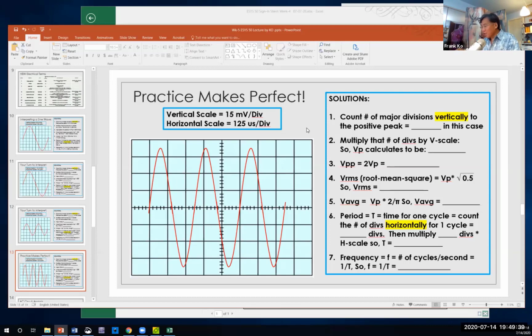If you put a straight edge, what you do is you get a piece of paper and you just put it as a straight edge. Does that straight edge line up with one of the hash marks, or does it kind of go in between? It looks like the very tippy top of that red waveform goes in between 0.4 and 0.6. So I'd call that a half of a division. So 3.5 divisions is a good count. And to make sure, would we count the horizontal divisions as 2.5? Looks pretty good to me. Okay, thanks. Sure.